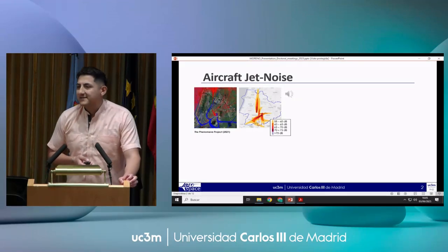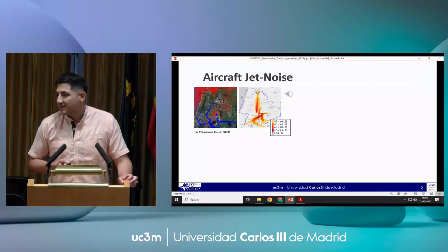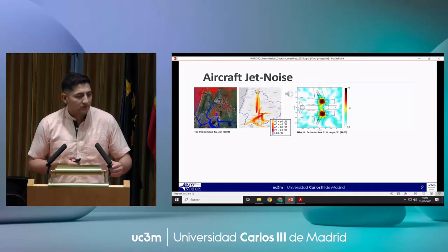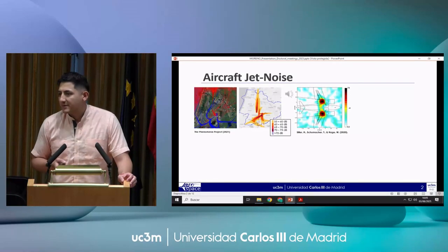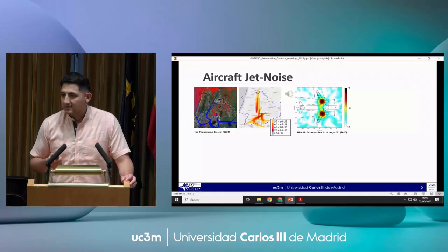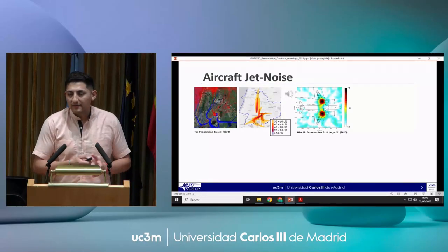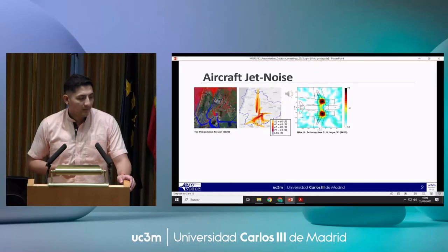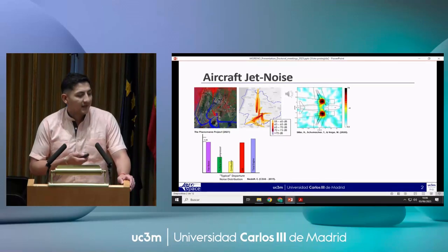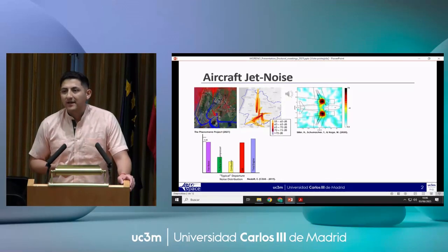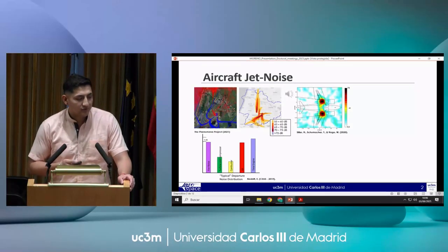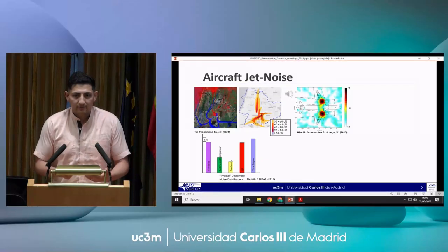As you could hear, there are several noise events happening at the same time, and it is quite difficult to disaggregate and separate all the noise contributions. There are some techniques, such as beamforming, that allow us to localize where the noise emission is located, along the frequency domain and also the time domain. By using this technique, Nesbrid could present the noise distribution, and it turns out that the fan, together with the jet, were the noisiest contributors. I'm talking about the takeoff phase.